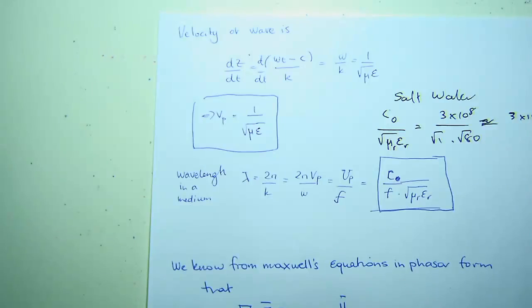That's significant, right? But if you decided to make it on FR4, which has a relative permittivity of roughly 3.5, 3.6, let's, for argument's sake, I can't do the maths in my head, say it's 4. Square root of 4 is 2. All of a sudden, if I wanted half a wavelength, I'm now at 3 centimeters. Then I can play another trick. Maybe that's still not good enough because I've got to put it into a mini PCI slot in my computer or my laptop or my colleague's iPad here, and I want to make it even smaller.